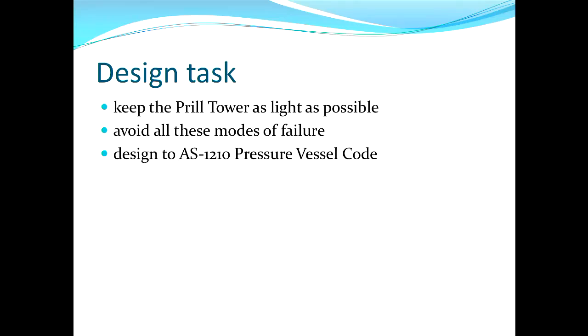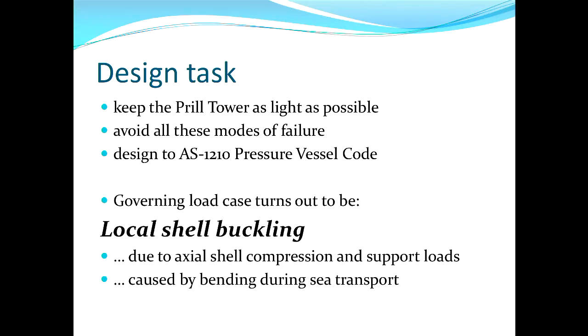What's the designer's overall task? Well, the big picture is we want to keep the prill tower as light as possible. We want to keep that wall thickness as thin as possible. We want to avoid all of these modes of failure, and we want to design the prill tower so that it'll conform to the governing pressure vessel design code AS 1210. Now, it turns out that the governing mode, the most serious mode, is the fifth one, the failure mode of local shell buckling that arises due to axial compression of the shell during sea transport. But all of them needed to be considered.